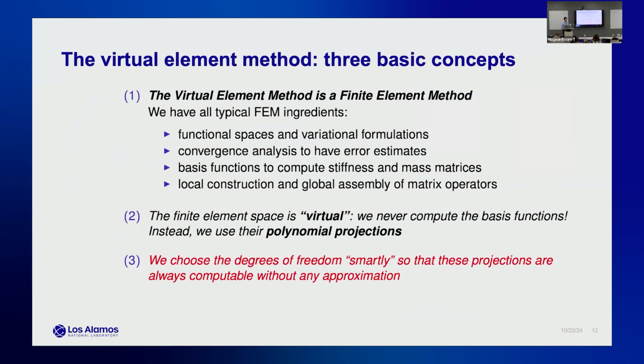So here are the three concepts of VEM. First of all, again, VEM is a finite element method. You use functional spaces and variational formulation. It has rigorous convergence analysis and error estimates. We build local stiffness matrices and distribute them to the global stiffness matrix. So it is the same procedure as what we do in the finite element method.